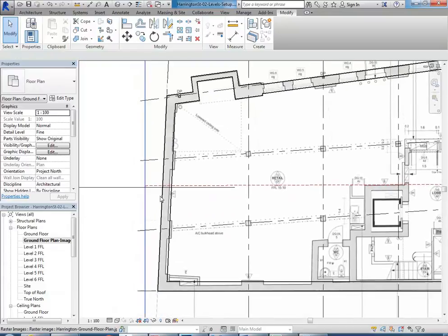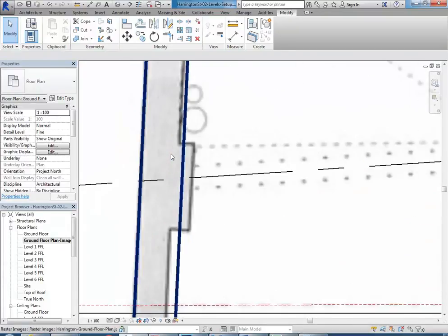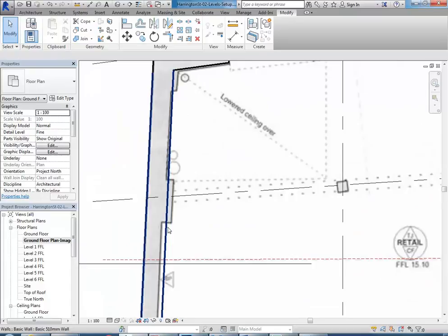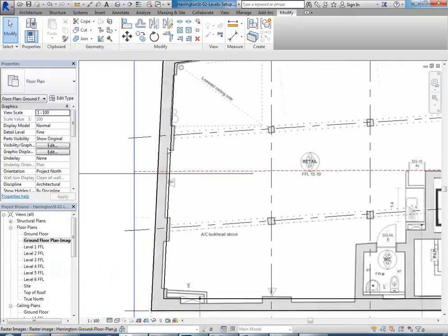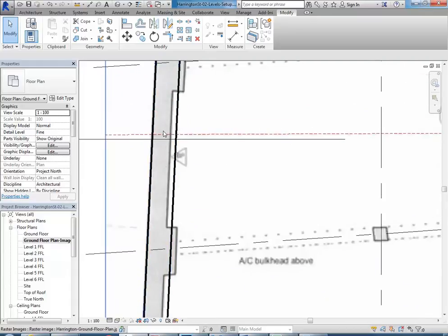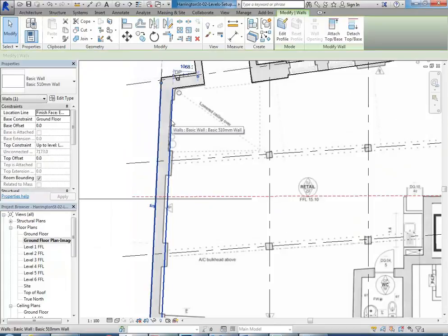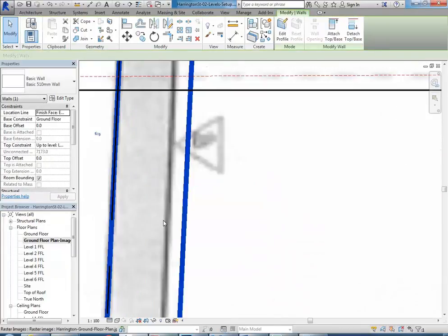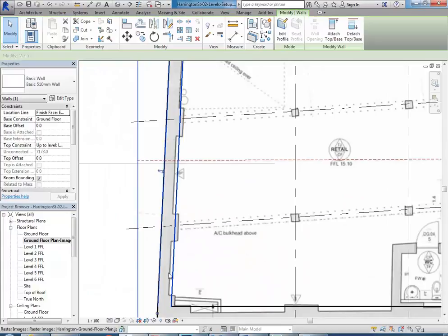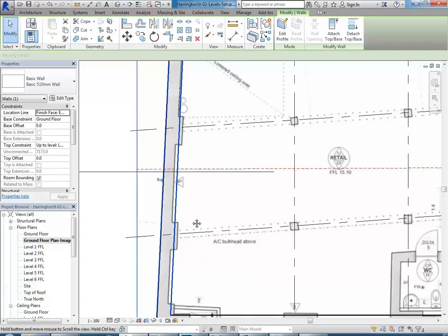Now, the piers should be done a little bit differently. So you've got all these piers that project, and again, I don't really think these drawings are all that accurate. I doubt very much that the wall thickness would change the way it's shown. If you look at the way this wall now appears traced over the drawing, it's obvious that they've actually got the inside line there not exactly parallel with the outside line. And I think that's just inaccurate drawing. So I would keep it with that wall thickness and just add the piers over the top.